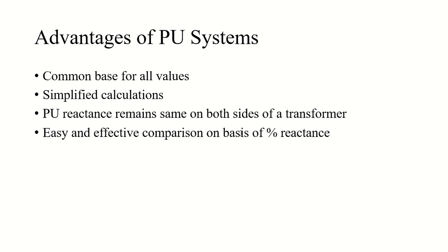Another advantage is that it is very easy and effective to compare on the basis of percentage reactances. Especially whenever you have multiple machines or multiple transformers, the calculation gets very easy with the help of per unit systems.